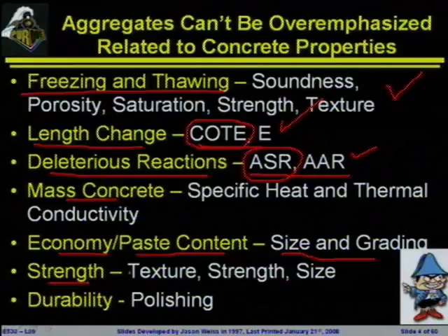Strength is going to be influenced by a few things. The actual strength of the aggregate itself, the size of the aggregate, which we'll spend a lot more time talking about later on in the semester, and the texture of the aggregate. A smooth aggregate is going to stick to the paste not as well as a rough aggregate. So the surface area, the way that it's crushed, is going to make a big difference in how well it bonds and what the overall strength is.